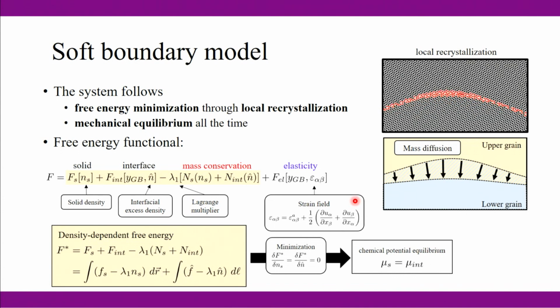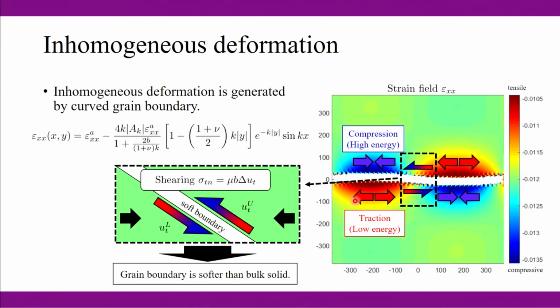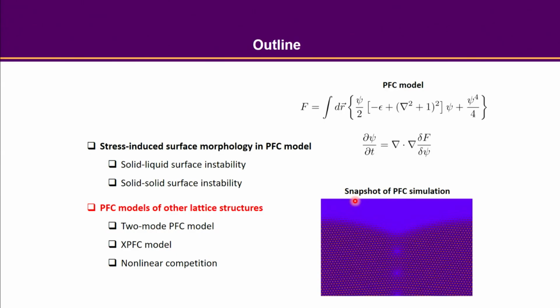So from that aspect, you can also model phenomena related to solid liquid interface. So solid-solid, solid liquid, and dislocation, elasticity or plasticity. Yeah, so that would be the strength of the PFC. Okay. All right. So that concludes the stress-induced surface morphology work that we have been doing with PFC.